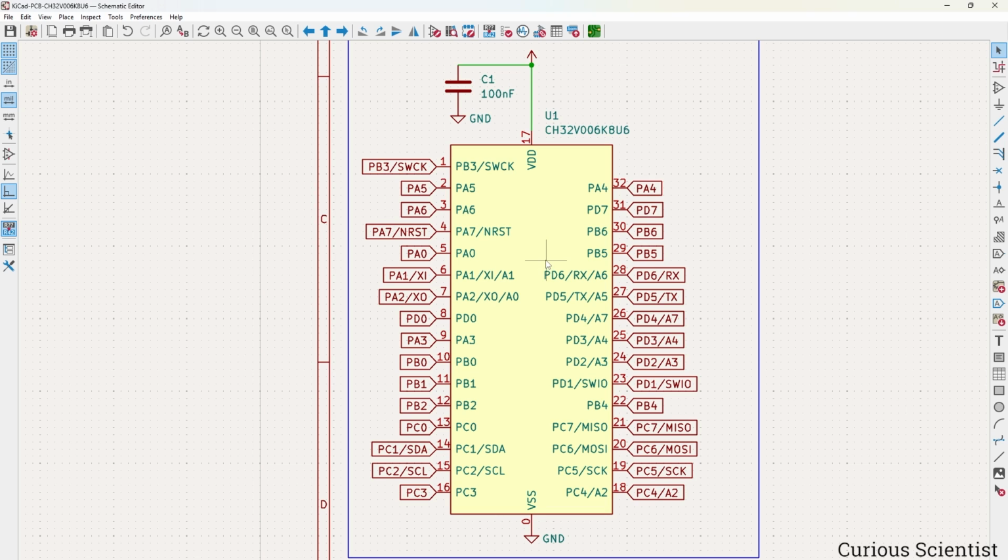It has one, but then every timing critical stuff, so for example, communication, timers, PWM and stuff like that, will not be as accurate as they would be with an external clock source. So I would rather add an extra unit, for example, an I2C or SPI AD converter, but I would still keep the external oscillator, and I would not rely on the internal oscillator just to gain 2 more ADC channels back. So this is that.